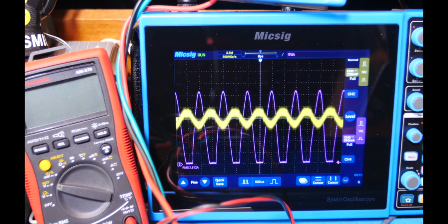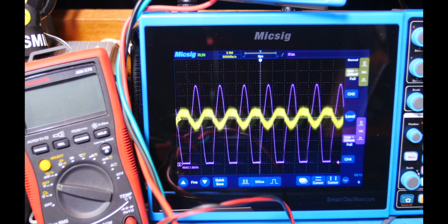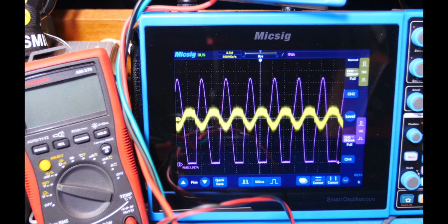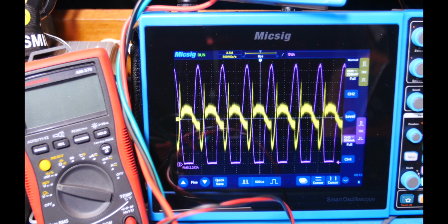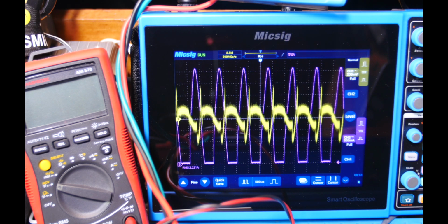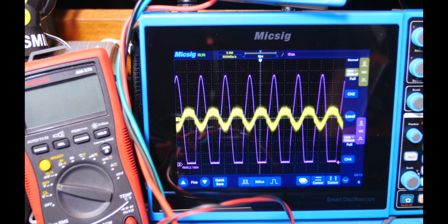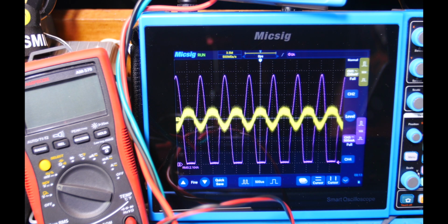So I'm still well below that little red light coming on the current limit. So let's, okay, right there it's starting to come on. And then you can see how bad the ripple gets on the power supply, and you can see how it starts affecting my signal too. But look at that, it's really pronounced right there. There's something happening every time a pulse occurs.